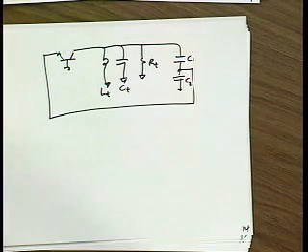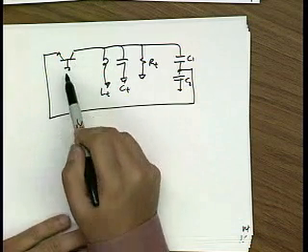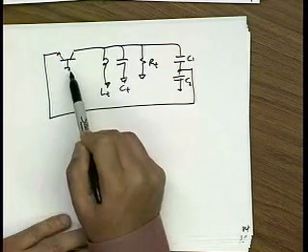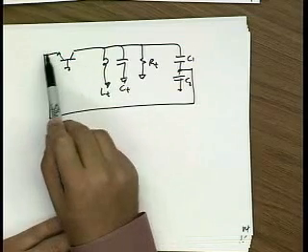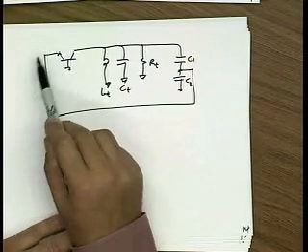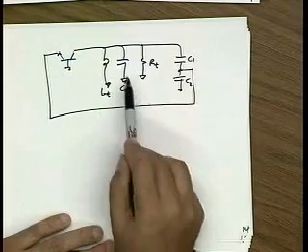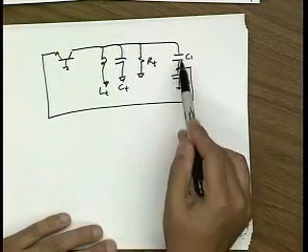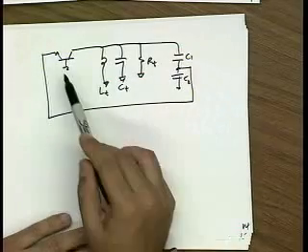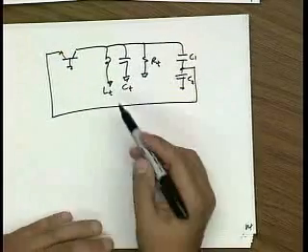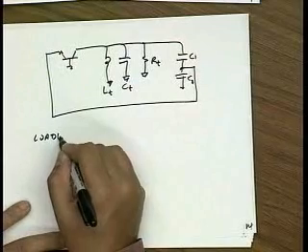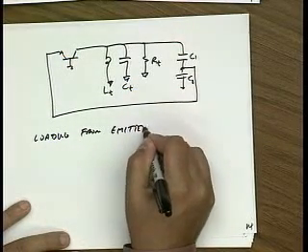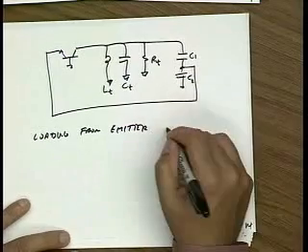That's right, yeah. So remember, in the common emitter oscillator, we're looking into the base, which is a high impedance. Now we're looking into the emitter, which is a low impedance. And that transformed impedance loads our tank. So that means I have to make my N ratio pretty big to avoid the loading. So now the loading from the emitter loads the tank.